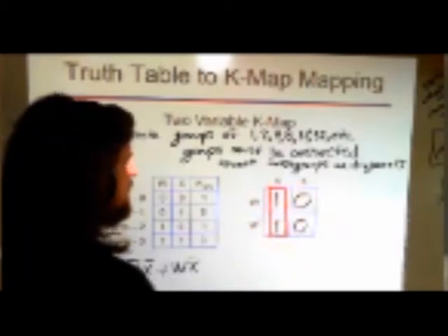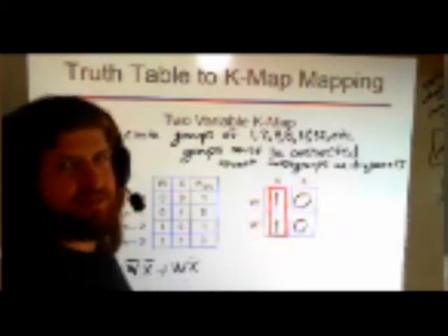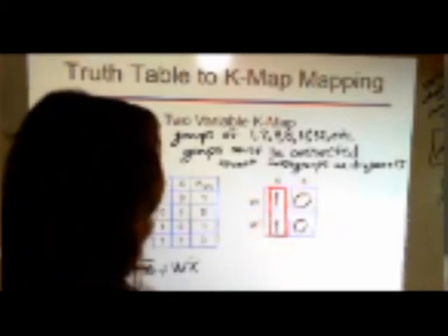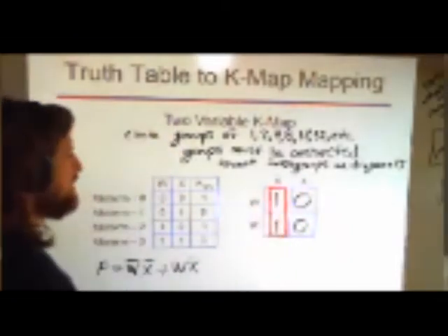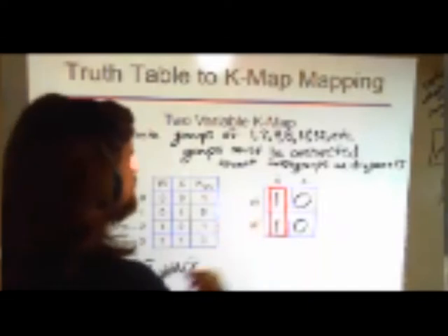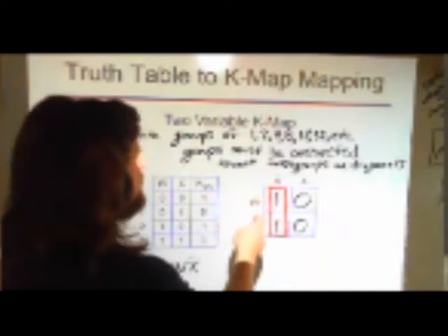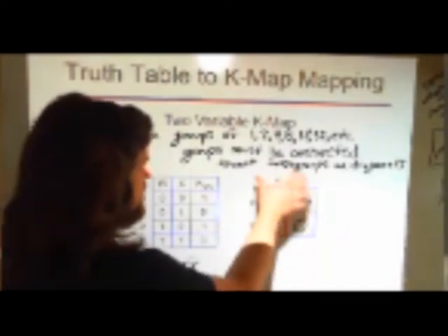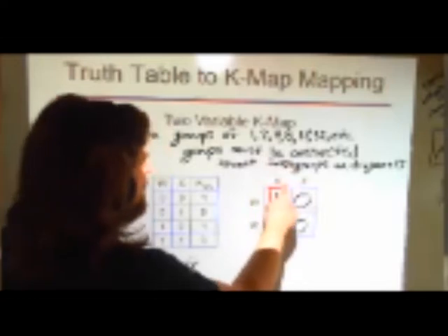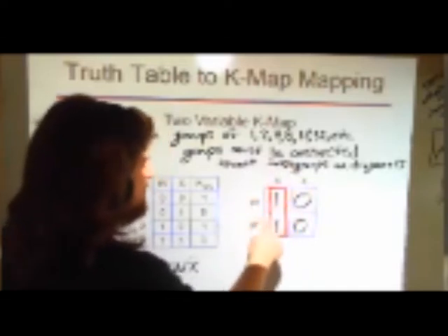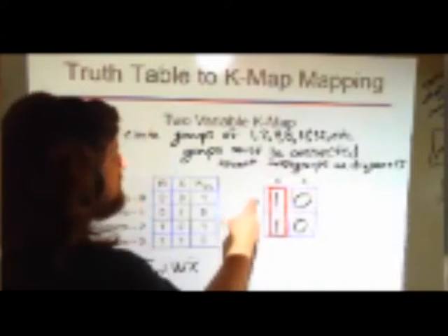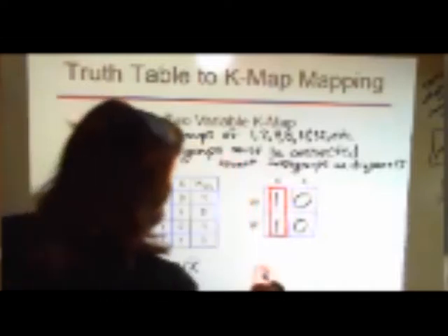So when we get to this stage where we've made one of these K-maps and we've circled the section, this is how we're going to do our Boolean algebra. This is what does it for us. The way it works is once we get our circling done, we take that circling and we say, okay, anything that within that circling included a change of that letter goes away. So in this example, that circling all occurred where X was 0, X not was the only case, right? W, this circling included both W is a 0 and W is a 1. When that happens, we can just remove that from the expression entirely.